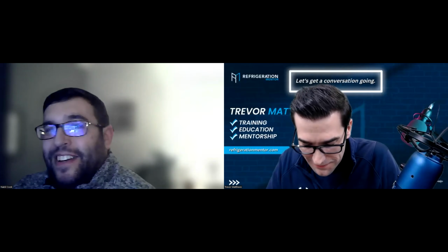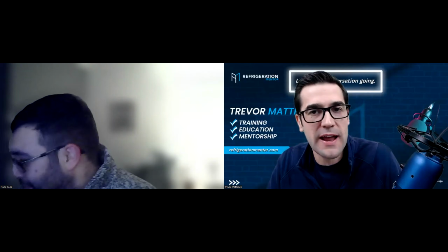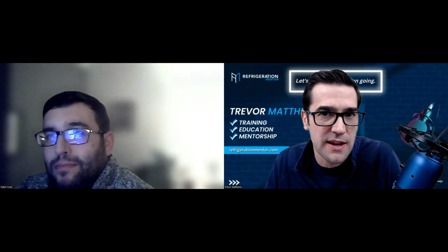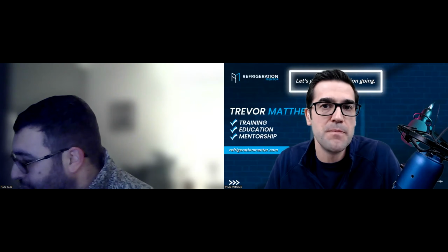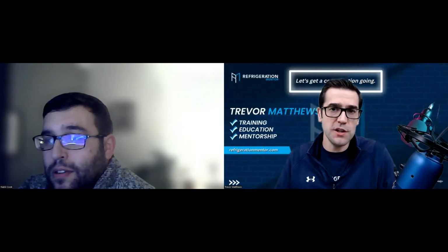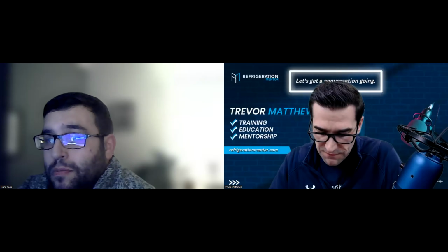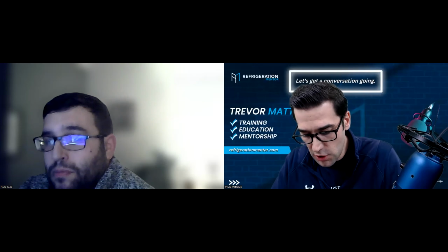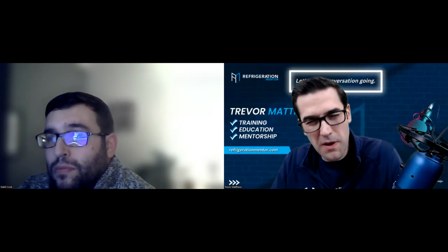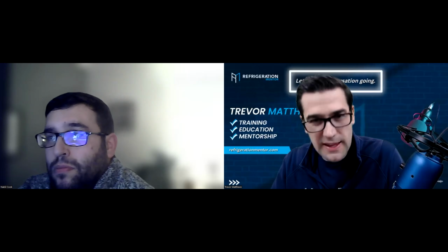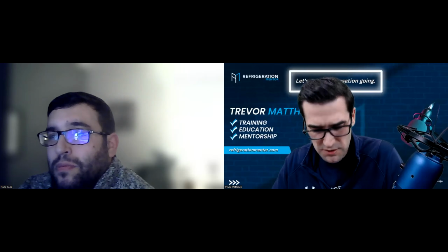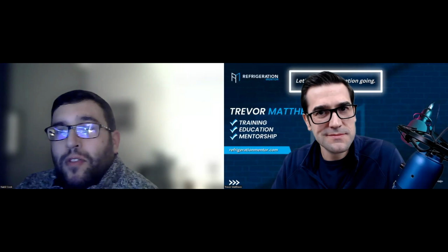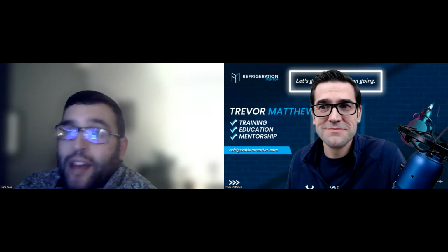And then on the low temp side, on that rack side, we're going to go with 25 kilowatts. So that's probably close to 85,000, 90,000 BTUs on the low side. Conditions we're going to use today, we're going to use plus 20 Fahrenheit, minus 7 Celsius, because this is the information you need, as well as on the low temp, we're going to do minus 20 Fahrenheit, which is around minus 29 Celsius. And the ambient, I think we said we're going to use 95, which is about 35 Celsius. Nabil? That's absolutely right, which is kind of familiar for a lot of users in Europe and also in the Americas, to be fair.